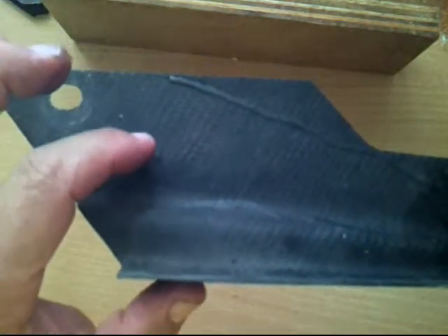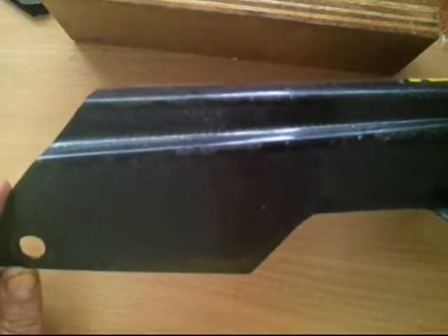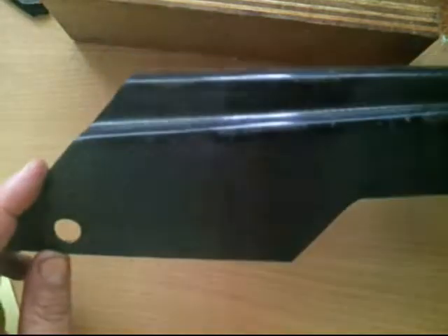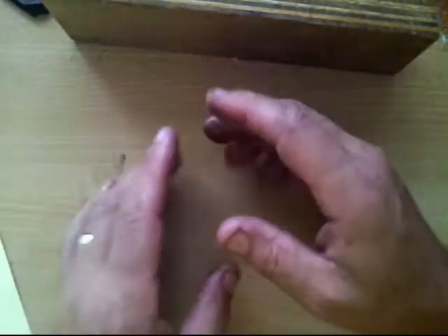And you look on the other side, you can see it doesn't have the glossy finish, but you can start to see the fibre appearing there. It's very tightly woven fibre. So that's an example of a matrix, and the strength of the product coming from the carbon fibre, and the matrix holding it all together and providing some filler material, and in this case a surface finish, and transferring the force onto the carbon fibre. Plenty of other examples of that. The reinforced concrete, which we'll talk about in just a minute.